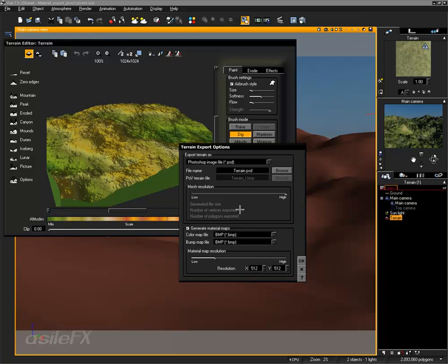That displacement map can also be used to create a normal map, if you're going to be using normal maps within another application, if you want to export this to another application. So that's a really cool way to be able to create a normal map. If you're not sure how to do that, there is a free tool available from NVIDIA that works with Photoshop that will create normal maps from height field based images or displacement maps, so grayscale images, and it will automatically generate normal maps.